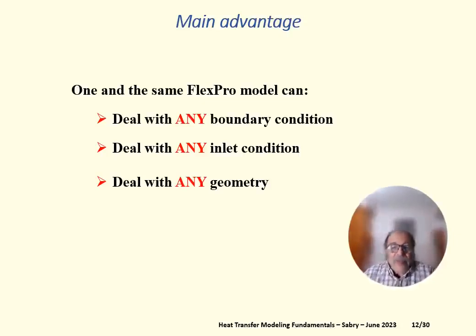The heat transfer coefficient model is not a boundary condition independent model. In fact, its name says that. We say the uniform heat flux heat transfer coefficient or the uniform temperature heat transfer coefficient. That is, we recognize that the heat transfer coefficient is not the same depending on the type of applied boundary conditions. It's not a boundary condition independent model, which means it's a very bad model.